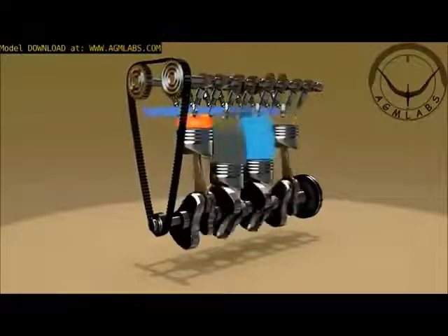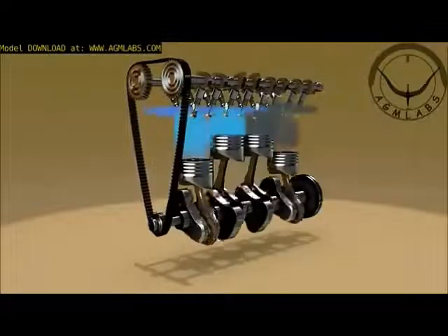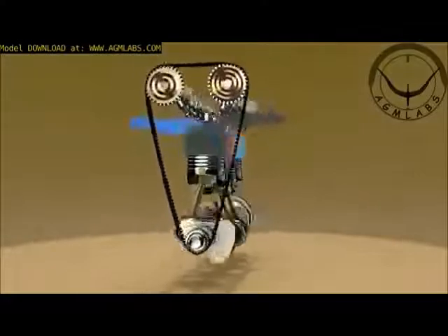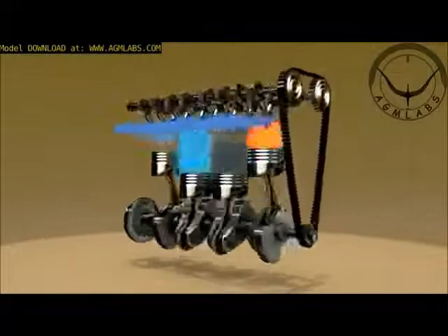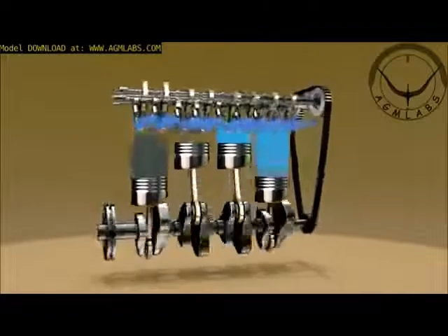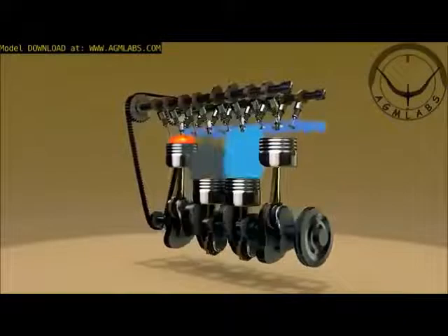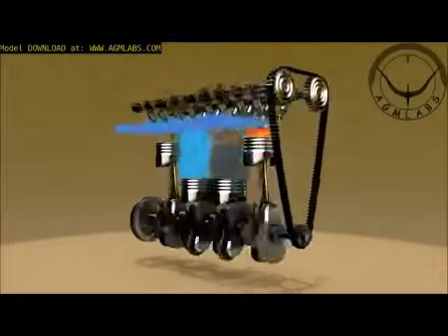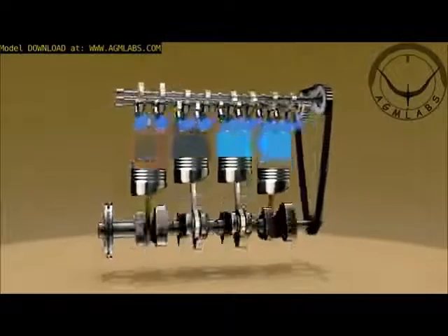Today, the internal combustion engine is used in motorcycles, automobiles, boats, trucks, aircraft, ships, heavy-duty machinery and power generators. A four-stroke engine is an internal combustion engine in which the piston completes four separate strokes: intake, compression, power, and exhaust during two separate revolutions of the engine's crankshaft, and one single thermodynamic cycle.